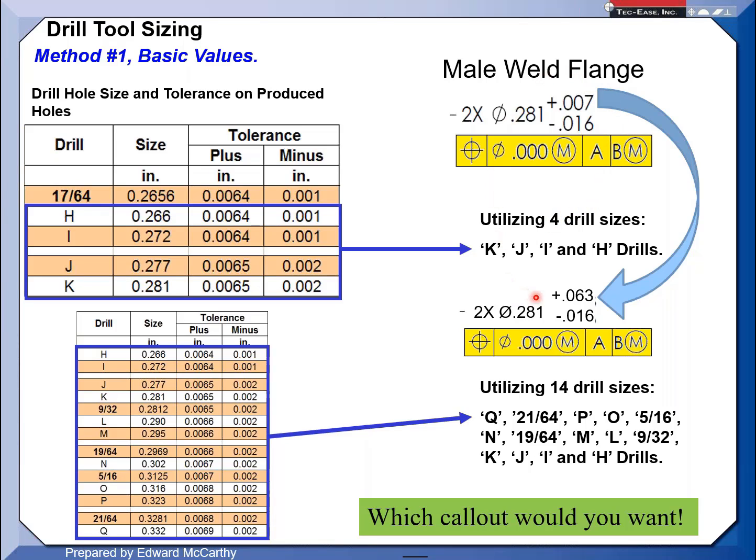It's kind of funny, a dear friend of mine at the company I was with struggles. He said, "Man, Ed, I've been doing this so many years, this just doesn't seem good to me." I'm like, well, if they make the hole bigger, and it meets the design intent, why don't we allow manufacturing all these drills as compared to 4 drills or 1 drill? That's really all I was asking here.